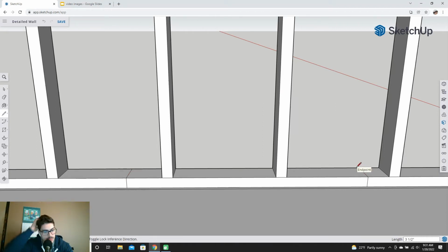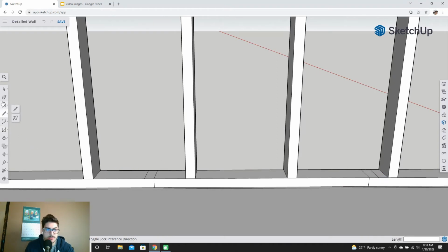So right at the limits of where your door is going to go, I'll go ahead and put my stud rectangles in here. Right wherever your door is going to go, you're going to have 2x4s to the left and to the right of the rough opening. That's what they're going to get mounted to, but you don't always bring these all the way to the ceiling. They're actually called jack studs.